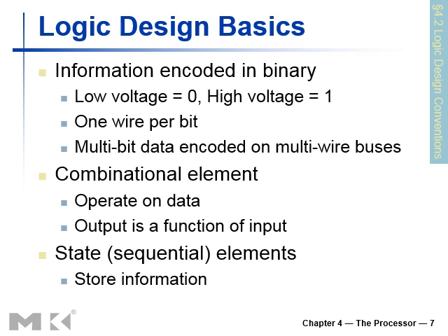And we're going to continue our discussion, which we stopped in the previous discussion while we were discussing the processor and its internal architecture. And we're basically going to design the single cycle processor. Till now, we have discussed the basic structure of a single cycle processor, and we've seen how the instruction cycle is processed, and then we're going to modify that basic structure depending upon the needs and requirements of our instructions.